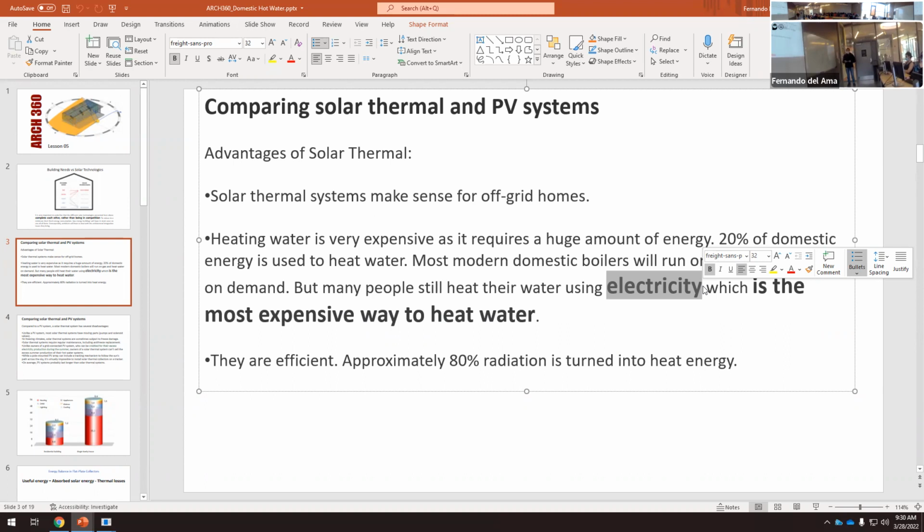It's a debate whether this building would be better if we had a hydronic system like a radiant floor, and we had more solar collectors. I think the building would be more efficient in that way than the way it is, having a huge PV array to generate electricity and use this electricity for the heating system. But we can talk about it. I can have an opinion, the other one can have another opinion. I will show the other one my numbers, the other one will show me their numbers, and we will make a decision with that.